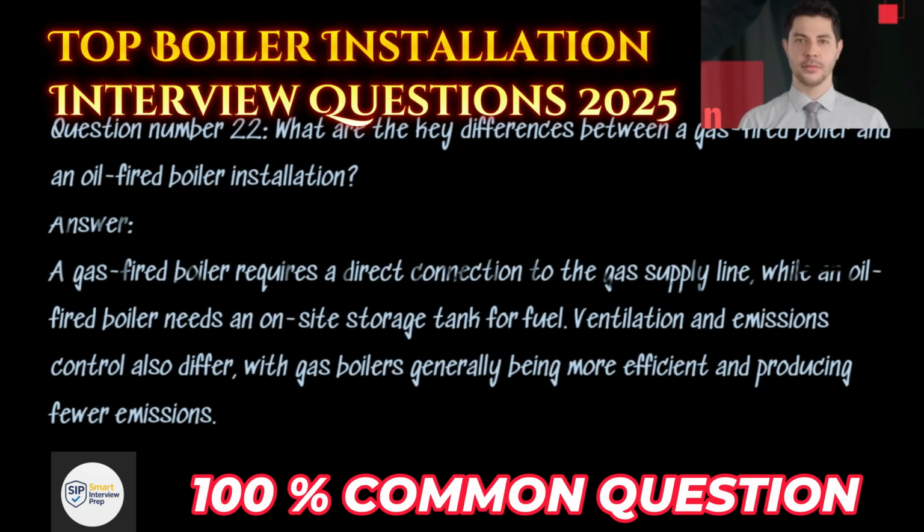Question number 22. What are the key differences between a gas-fired boiler and an oil-fired boiler installation? Answer. A gas-fired boiler requires a direct connection to the gas supply line, while an oil-fired boiler needs an on-site storage tank for fuel. Ventilation and emissions control also differ, with gas boilers generally being more efficient and producing fewer emissions.